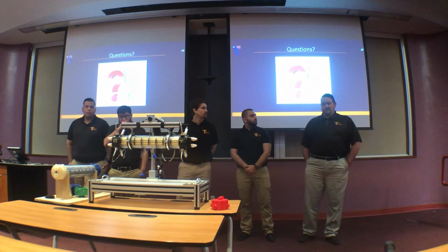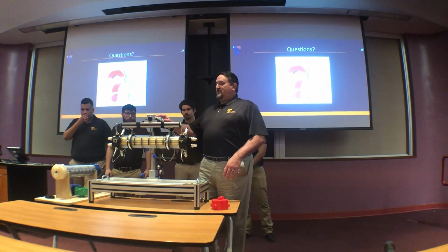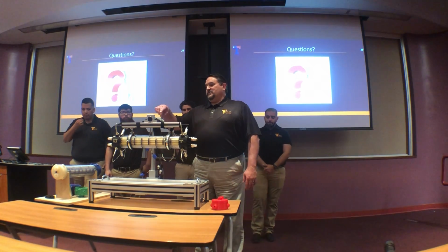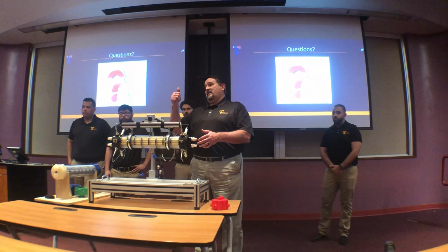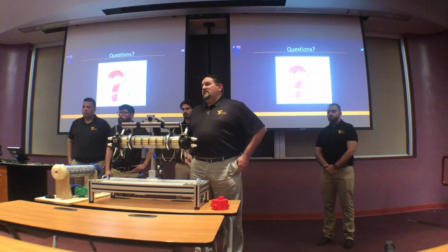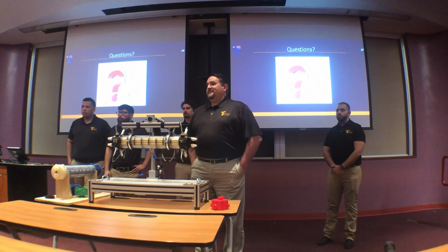Yeah, we initially hook up the hot and cold like we were talking about before. A couple screws get loosened here. This can get rotated 90 degrees to purge any air trapped in it, so we push it up through the hoses, through the outlet. You'll rotate and fill from the bottom, and then connect once you're purged.